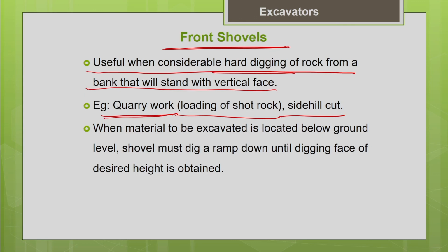If you want to use this machine for excavating below the ground level, then what are you supposed to do? You have to do the ramping down. That means the shovel must dig a ramp down into the material until a digging face of the desired height is obtained. Then only will it be easier to use the front shovel.